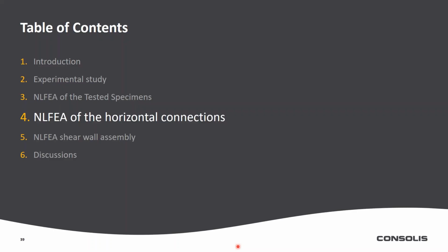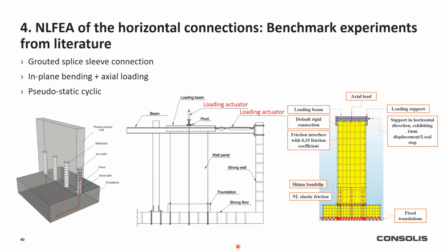And now let's discuss a little bit about the horizontal connections. The horizontal connections chosen for the study are implying a grouted splice sleeve. We had test results from the literature, tests that are subjecting such connections in axial loading and combined with bending.